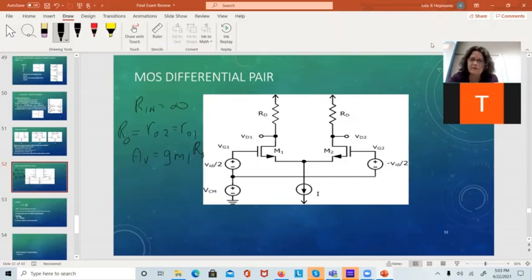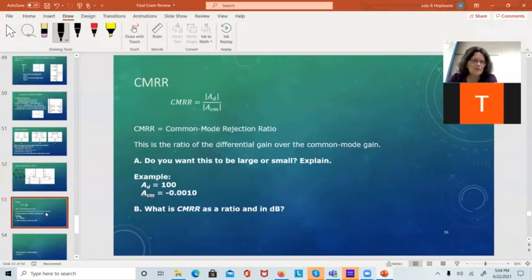If I have this stage in my circuit and I have something else connected to it, I can use that two-stage model of the amplifier and figure out what the overall gain is of a two-stage circuit without having to look at all those horrible transistors in there. I can model it as an input resistor, an output resistor, and a gain, and not have to think about the transistors.